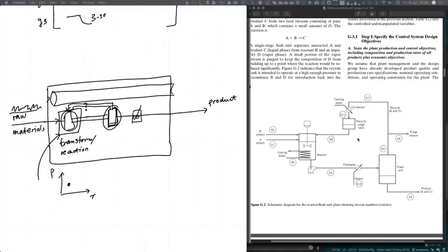And so what actually ends up happening is we operate at some point that is away from the ideal operating point. And in the single variable version of this, we may want to operate at some target pressure, and the way that these things typically work is that actually there's an upper bound on that. Almost all of the time, those things are bounded. So the best operating temperature and pressure is often the highest temperature and pressure, or there's some other operating constraint.